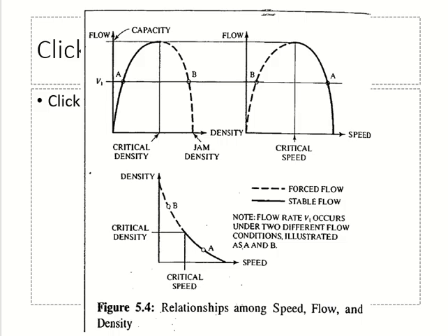So when you see the dotted regions, that means the vehicles are blocking each other. They are making each other stop. Before that, they are moving in a stable manner, continuously moving without any stoppages. So we call it stable flow, and the other one is called forced flow because people are forcing you to stop. Clear?